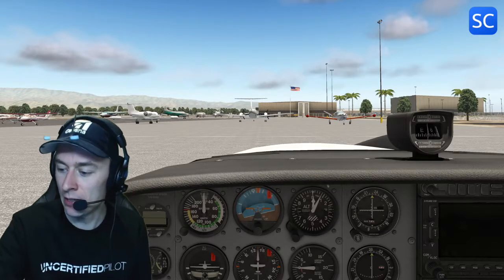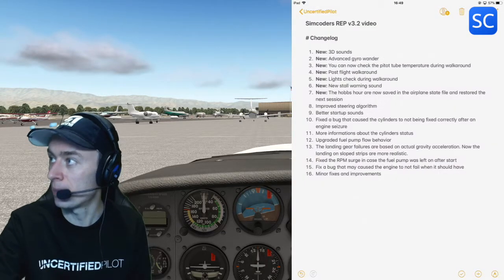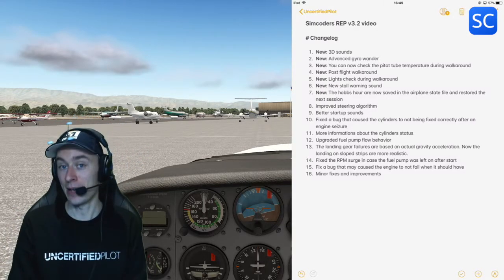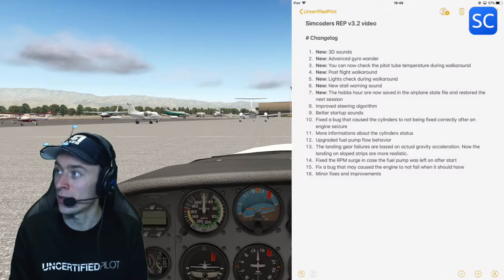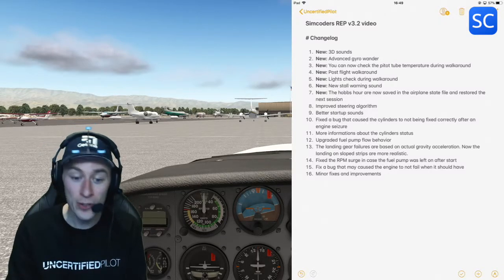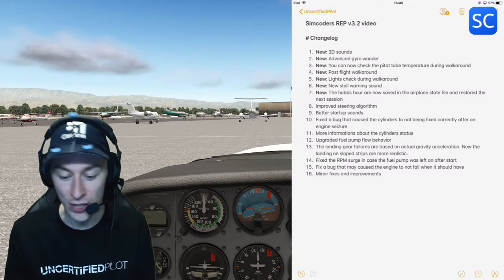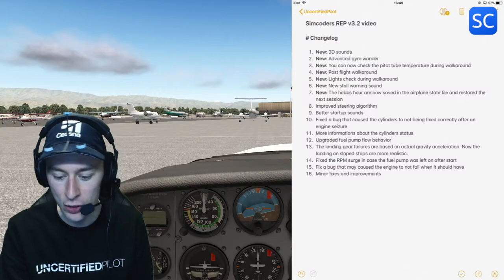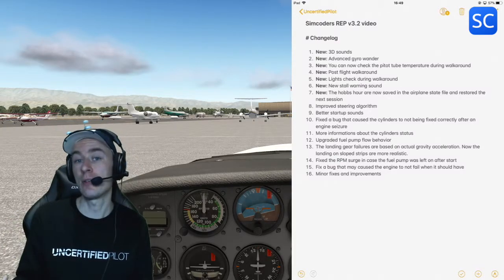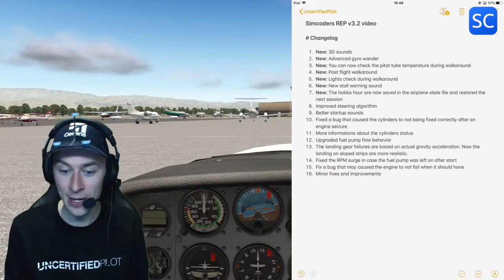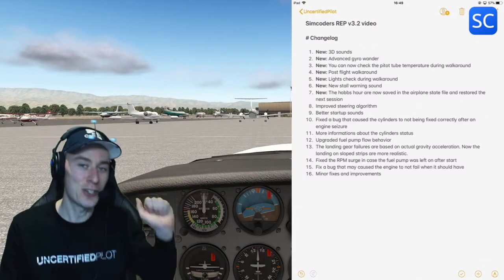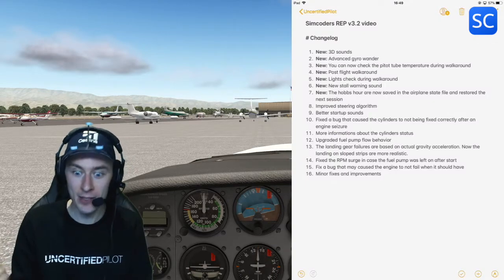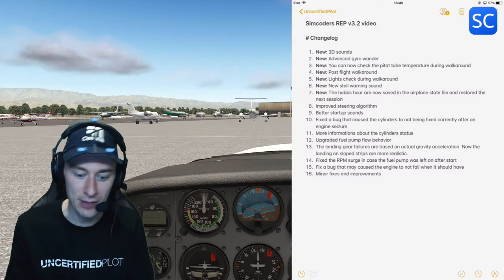Okay, having said that, let's also have a look at the changelog, because now version 3.2 is current. We've got new 3D sounds, very, very nice. Those sounds are now much more directional, and I will show you in just a sec. We've got advanced gyro wander, very relevant, very important. You can now check the pitot tube temperature, also very important, especially if you are an IFR student pilot. You can now virtually touch the pitot tube to see if the pitot heat is actually working. I mean, you can flip the switch, but it doesn't mean that the system is actually working, and that's why it's a very important check.